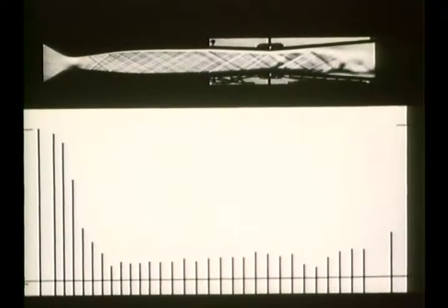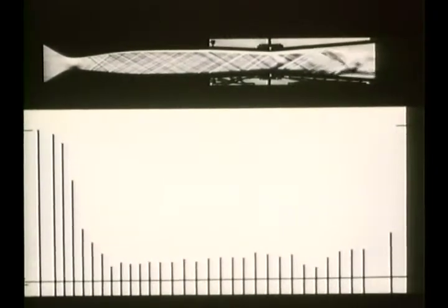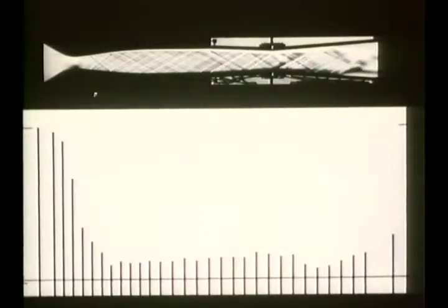The wave pattern ahead of the second throat and the pressure distribution show that the flow is supersonic all the way from the first throat to the terminal shock wave. If we now close the control valve slowly, we drive the shock pattern upstream toward the second throat, where the Mach number is lower than the test section value because of the supersonic compression.